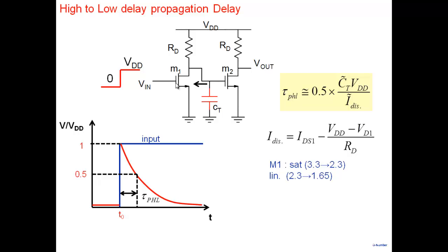If you look at this transistor M1, the moment you switch this on, the voltage here is VDD, and this node has not yet discharged. The voltage here is also VDD. This is at VDD and this is also VDD. The transistor M1 is in saturation region. So it starts off in saturation region, and it will remain in saturation region till the voltage here drops to VD sat.